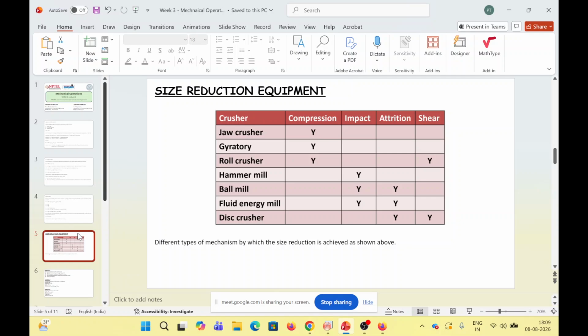So there are different types of factors that usually affect the kind of material or the product that you obtain from a ball mill, starting from the density of the balls, the weight of the balls, the residence time, the speed of revolution, the kind of particles that you are going to inject, the type of the balls, I mean the material with which this grinding media is made.